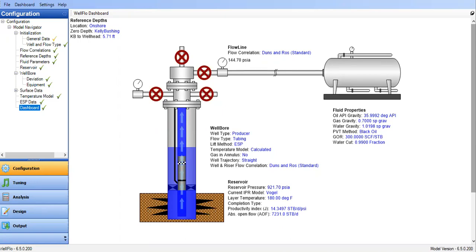So, starting from opening only one reservoir, in that condition I have the ESP operating, and later on I want to open another reservoir, a different, hydraulically disconnected reservoir. I want to see how big the production improvement is that I can obtain by opening a new reservoir and performing commingled production. So I have the model with me.